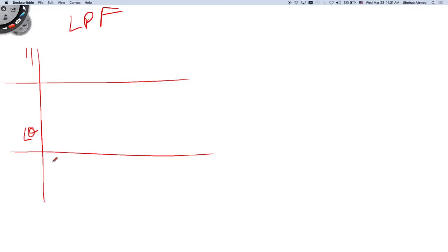So at low frequency, I expect the phase shift will not change because the signal wants to pass through as it is. And then at high frequency, again, it's an RC circuit. So I know that at some point the capacitor will be the dominant component acting on the AC signal, and it will phase shift the signal by 90 degrees. So I know that this is what's happening. And I know the slope of this is going to be 45 degrees per decade.